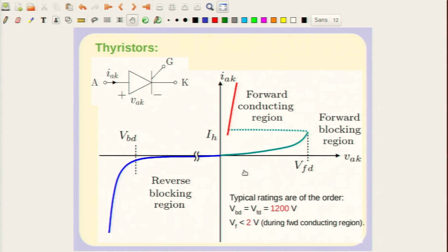So, what is the advantage of this? A thyristor can be controlled, unlike a diode bridge. A diode can switch on whenever the voltage across it becomes positive. There is no other control, it is completely dictated by the conditions in the circuit to which it is connected.